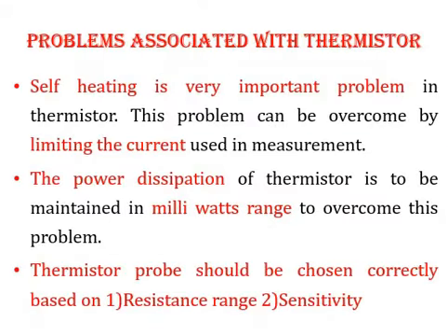Next, problems associated with thermistors. Even when we are using the thermistor, it itself creates some problems. That is self-heating. When the thermistor is placed in a hot environment, before measuring the temperature it starts reacting to the ambient temperature.